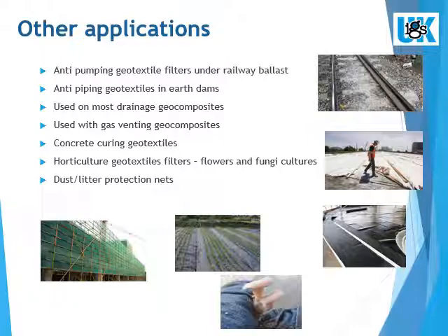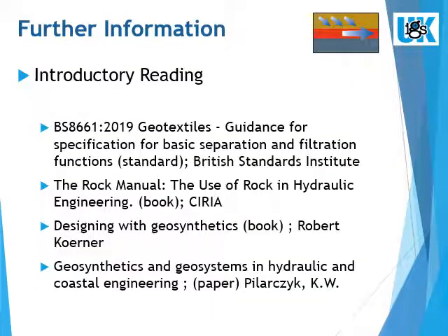We have looked at filtering average soils in the UK to prevent clogging of stone filter drains. Also high flow reversing filters in rock armour revetments applications, and then closing of silt or sludge lagoons with tight filters holding back the silt fraction whilst forcing the silt to dewater. Some of the other applications which may interest you are mentioned above. Further guidance on the design and execution of geosynthetic filter solutions is as shown in the list above.